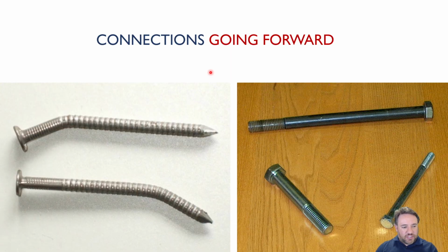Okay, so those are all of the different types of connections that I just wanted to introduce you to. Going forward, we're going to learn specifically how to design nailed connections and bolted connections, since these are the most common typical connections. Glued-in rods and self-tapping screws are not really in the design guideline. There are some proprietary methods to design those types of connections. It's come a long way, certainly in the past 5-10 years. Even since we did that study, I think it's come quite a long way.